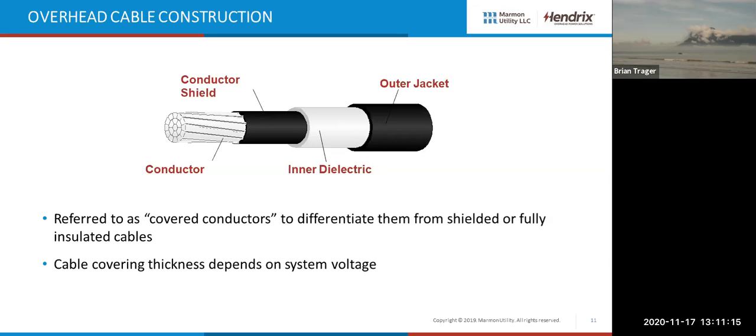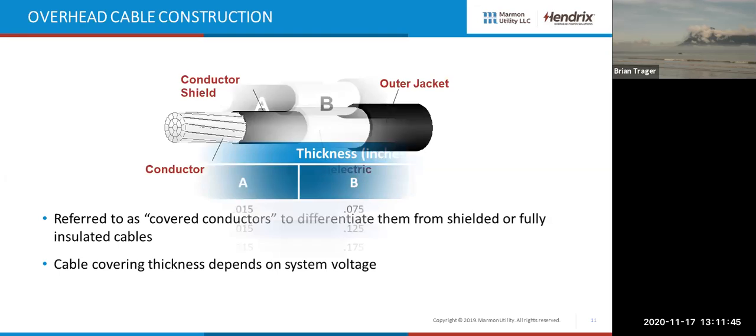It is also where we put our track resistant adder and also where we put our UV inhibitor, and that UV inhibitor is a chemical UV inhibitor. It's going to put a chemical umbrella on top of the molecular chains and protect them from UV radiation. And that's different than the carbon black that some manufacturers are adding that's fugitive and oxidizes, has all kinds of problems. But anyway, that's a 3-layer construction.